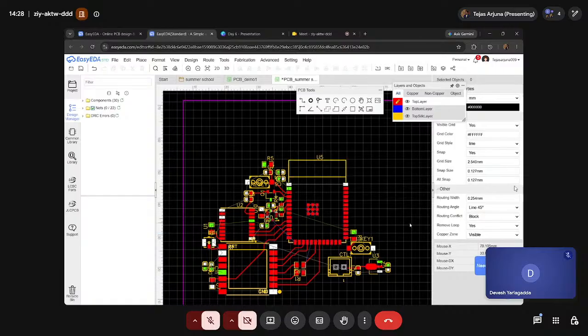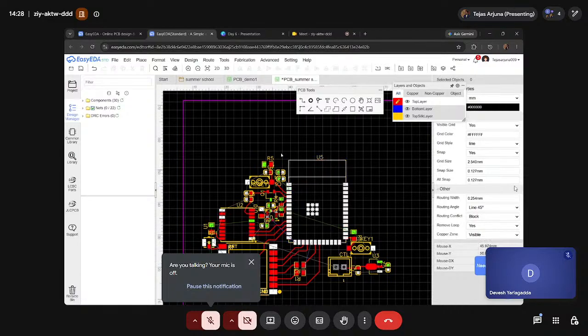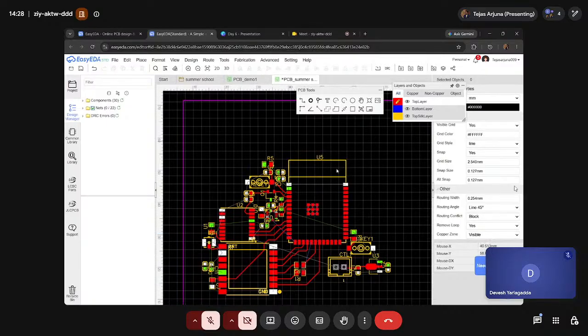That is the point. So the second point I wanted to tell is, if you want to route the VDD part also, we can do them in the bottom layer. There's space there. We did almost all the signal trace connections except two of them. If you want to do the VDD traces, we can do them at the bottom, but that also increases the loop area. We should minimize the loop area as much as possible. And there's a thing you must keep in mind, that a 2-layer PCB has the same thickness as a 4-layer PCB. So the thickness of the PCB does not change if you change the layers.